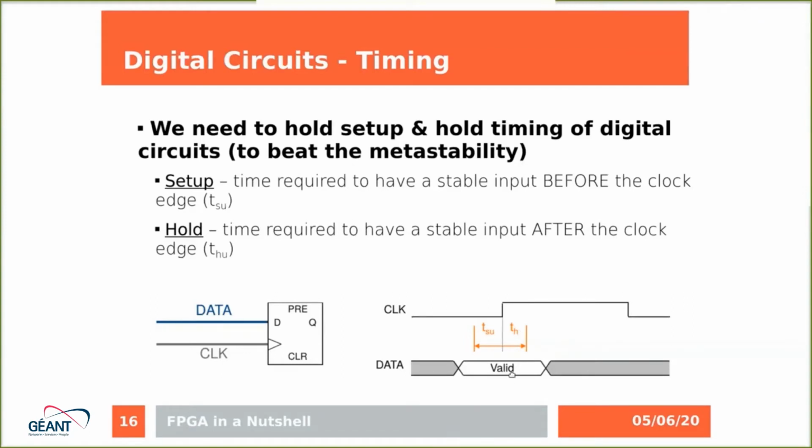This is a physical constraint of digital circuits, because if you don't meet this timing, then you will fall into the metastability issue, which isn't good, because during metastability you are not able to decide if the output of this block is 0 or 1. So this is the physical requirement of the technology.